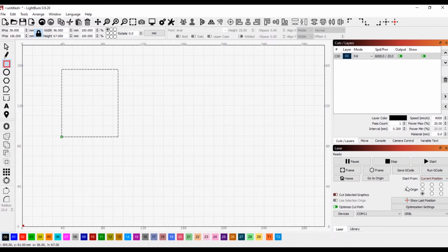Now these next settings down here, if you remember earlier I briefly spoke about the squares in this bottom left hand corner. As default this may load up and say absolute coordinates, and as you can see I've just switched that to absolute coordinates and the green dot has come back down into the bottom corner. If you have limit switches, as I say, it will always treat this as your default. But if you don't have limit switches, as often is the case on a 3018 Pro, you will need to change this to current position, and what we should see is that green box in the bottom left hand corner will jump up to the shape above it.